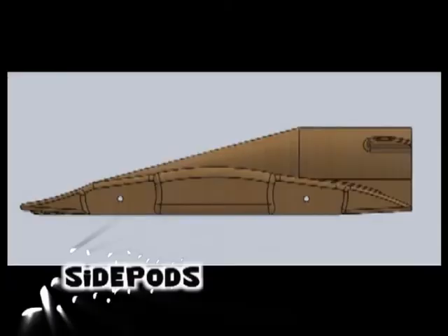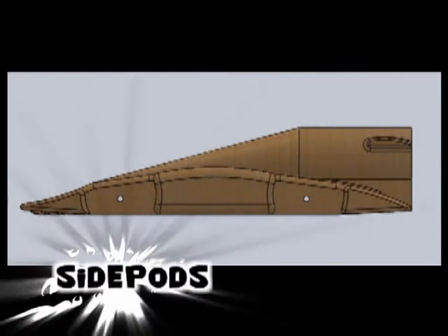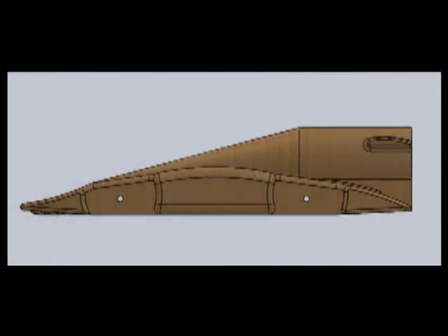The side ports were made curved upwards to allow the air to flow fast. Based on aerodynamics concept, faster air produces lower pressure. With the large power force produced by the carbon dioxide gas, the air moves fast as it flows through the car. This will also make the air flow in streamline and produce less turbulence.